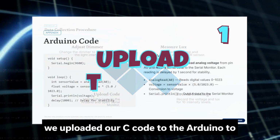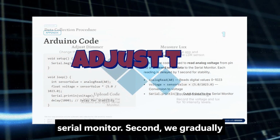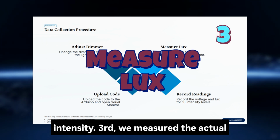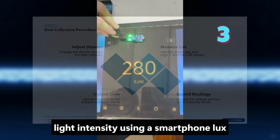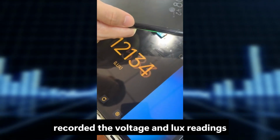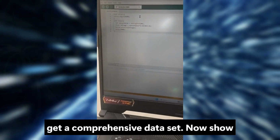First, we uploaded our C++ code to the Arduino to read the analog voltage and open the serial monitor. Second, we gradually adjusted the dimmer to change the light intensity. Third, we measured the actual light intensity using a smartphone lux meter app, ensuring it was perfectly aligned with the sensor. Finally, we recorded the voltage and lux readings across 10 different intensity levels to get a comprehensive dataset.